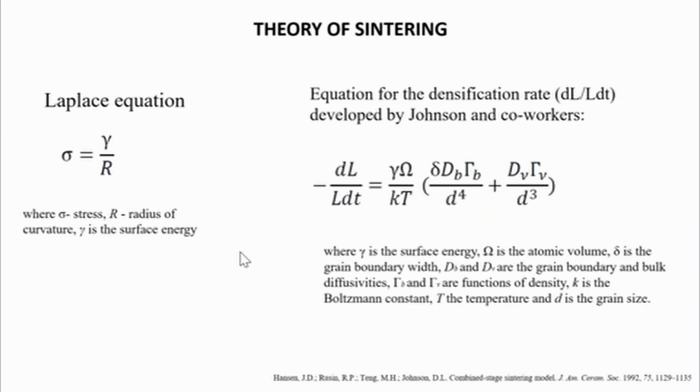From the kinetic point of view, we expect enhanced densification for processes that display a direct grain size dependence. For sintering, this dependency may be illustrated using the equation for the densification rate developed by Johnson and colleagues and used for all stages of sintering.